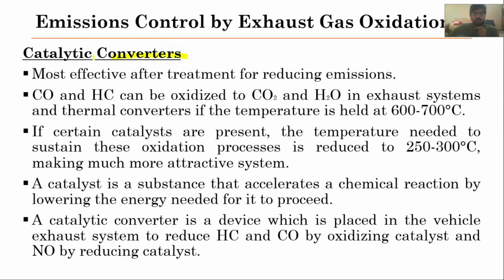As the name suggests, in these converters there must be some catalyst, and because of the presence of the catalyst, the requirement of higher temperatures needed in the thermal converters has been reduced. We do not usually require temperatures like 600 to 700 degrees Celsius for the conversion of carbon monoxide and unburned hydrocarbons into carbon dioxide and water vapors.